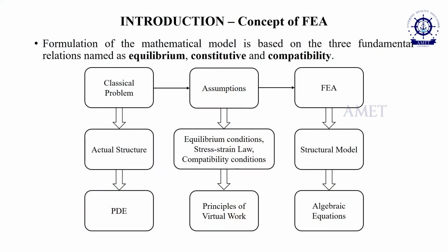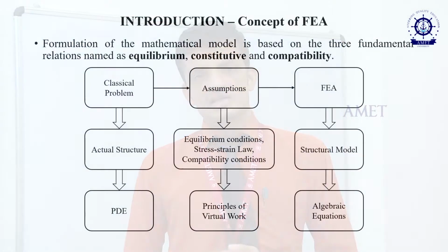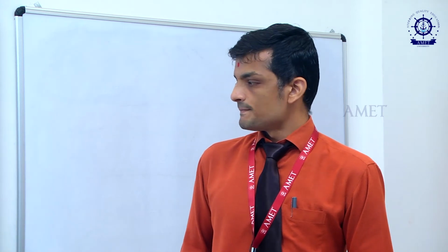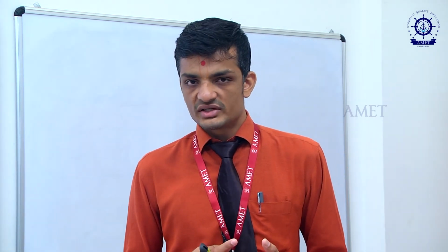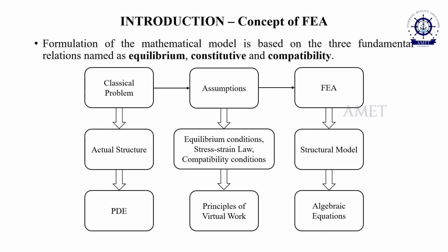In any structural analysis, the primary component is the displacement. So you have to have the relations between the various physical properties. Stress and strain, how they are related together, how the displacement is related to the strain, so that once you find the displacement, you find the strain value, and from the strain you get the stress. Once you have the stress value, you can derive the internal forces and moments coming on the structure. For that we have something called equilibrium conditions, stress and strain laws. For example, Hooke's law, and once you form those compatibility conditions and the equilibrium conditions, you have to apply the principle of virtual work, those energy methods, to further simplify.